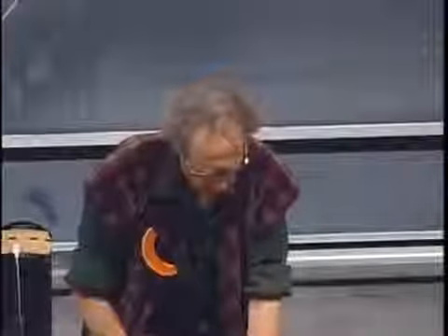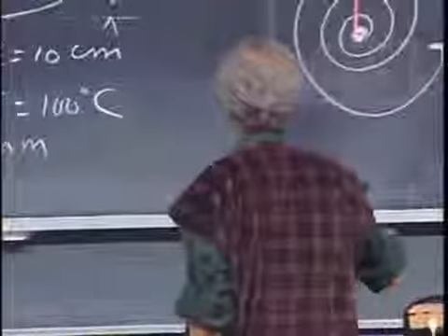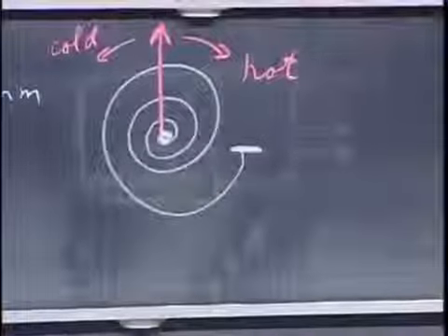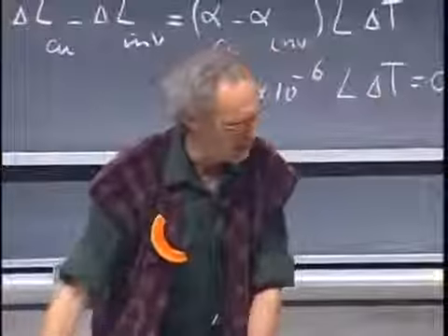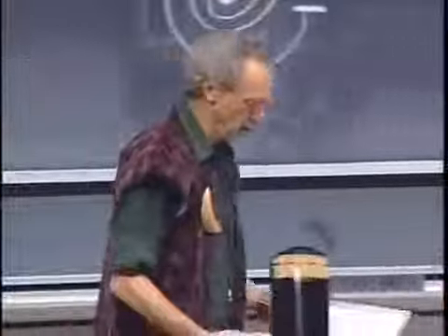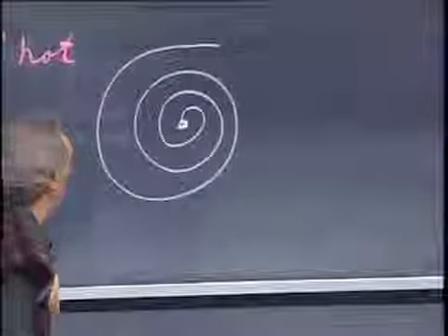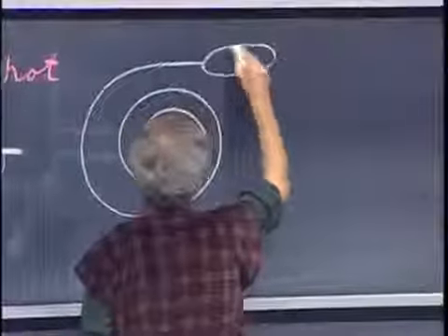Thermostats in your dormitories, of your heating systems and also perhaps of the air conditioning systems, almost all have a coil like this in there. It's an extremely ingenious device. It has a coil, and at the end of the coil is a little glass tube. It's only 1 centimeter large, and there is mercury inside. So the coil is like this. Bimetal. And at the end here is a glass container, and there is some mercury.